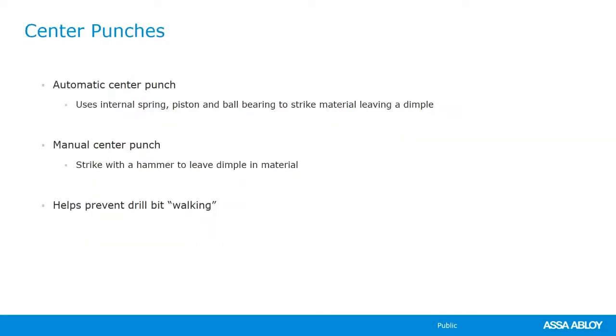In order to drill an accurate hole, though, we need to make sure that our drill bit doesn't walk, doesn't move from the place that we wanted to make that drill. We can't just put a pencil line on the door and then put the drill bit up there and start drilling immediately. Most of the time the bit will move, and sometimes it can move by 3/16 of an inch, 1/8 of an inch easily. And now our whole install is skewed and off just a little bit. And that can greatly affect the durability and the longevity of that particular piece of hardware.